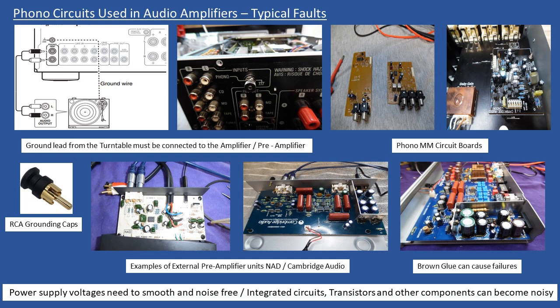And even on the early Creek Audio phono stages, the 4040 series, it was normally the op amp that tended to go noisy, and you can replace them, and even now they are readily available, or some people will actually install a more improved modern up-to-date operational amplifier. Pinouts tend to be the same, you don't need to modify anything. And then also capacitors or transistors. These phono preamplifier stages, you don't really come across field effect transistors in there, but be aware, like a bipolar transistor, a field effect transistor can also go noisy.